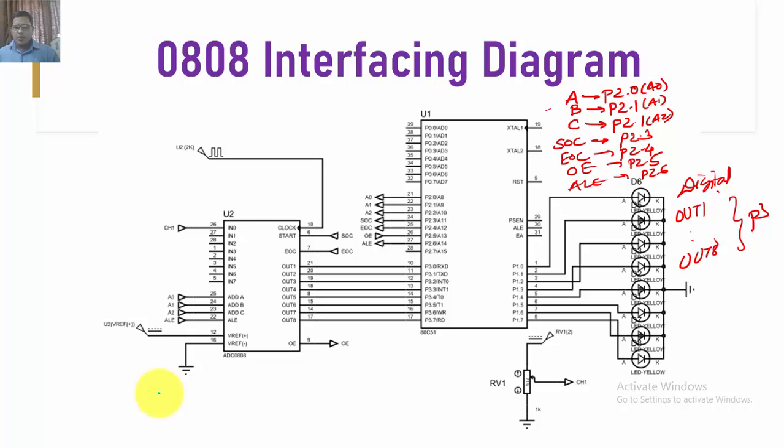As usual, this port is going to represent the sensor. Whenever the resistance of this is varied, the input given to the channel is going to change. Consider that the sensor is connected to the first channel of the 0808, IN0. Here I am going to connect a 1 kHz clock externally, and the analog data converted by ADC0808, present in digital format on the output lines, is read by port P3.